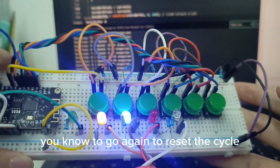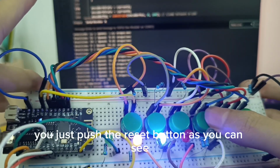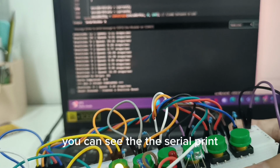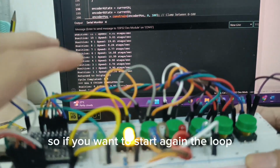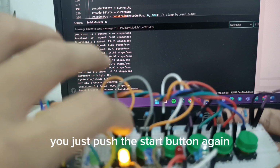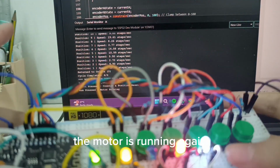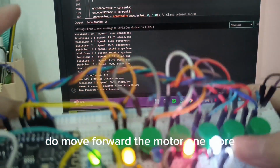If you want to go again, to reset the cycle, you just push the reset button. As you can see, when you push the reset button, the serial print shows the counter and position are reset. If you want to start the loop again, we just push the start button again, and the motor is running again. So you can just do the loop, moving the motor forward.